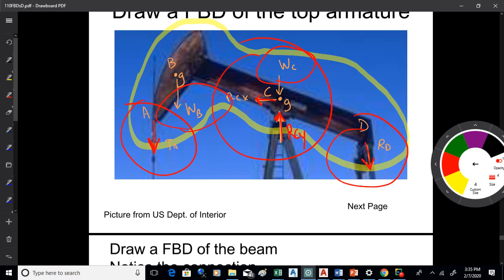The potential would be in both directions, though, wouldn't it? Correct, yeah. I guess one or the other, and my signs will prove out which way it goes. So I'm not worried about whether I show it left or right. But I do want to put it on there because I'll prove it's 0 when I go sum of Fx is 0. Then it'll come out to be 0. So I don't like mixing the analysis and the drawing of the free body diagram. I just want to draw a free body diagram. I see a pin joint, I get an X and a Y force. That's as deep as I think about it. I slap it on there. I'll figure out that 0 later. That's not a problem.